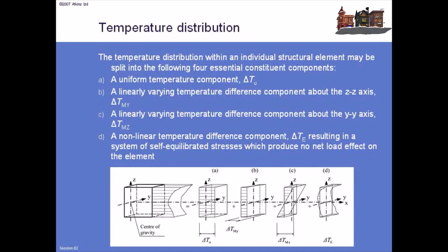But one other component that the Eurocode introduces is a horizontal temperature variation, which we haven't previously had, and it works in a similar way to the vertical temperature profile, and it shouldn't be used on all structures. It's basically only really intended for masts of things like cable stay bridges or very, very tall piers, where in the past we thought, well, there must be some differential temperature effect on this mast or pier because the sun's shining on one side, but there hasn't been anything in the code. So now that's covered in the code.